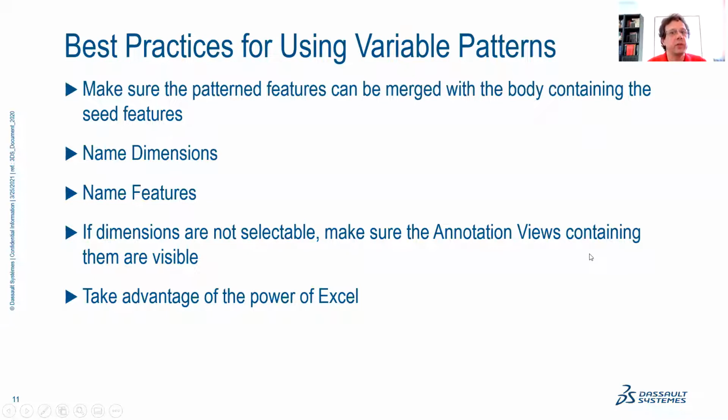Take advantage of the power of Excel. Once you figure out roughly where the dimensions are going to be, and what the logic is to add the dimensions, you can use the full power of Excel with if statements, with lookup tables, lookup formulas, VLOOKUPs, things like that, to make your life very, very easy. So allow Excel to make the hard decisions and simply import the table inside SOLIDWORKS.